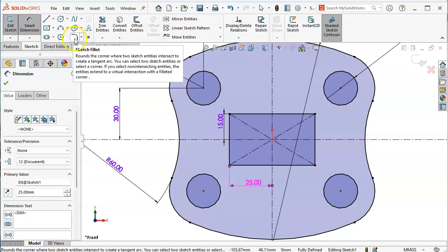And one of the things that comes up with putting the fillet in, we have to choose if we're going to include the fillets in the sketch. And if there's a few, it's not a bad thing. Sometimes it's easier if there's a lot of fillets to make it a fillet feature and just leave the corners square.